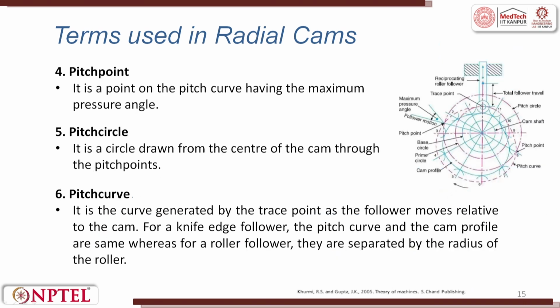Next, pitch point. It is a point on the pitch curve having the maximum pressure angle. Pitch circle is a circle drawn from the center of the cam through the pitch point. So, center of the cam to the pitch point, it is called a pitch circle. Then the most important thing is the pitch curve. So, this is called the pitch curve.